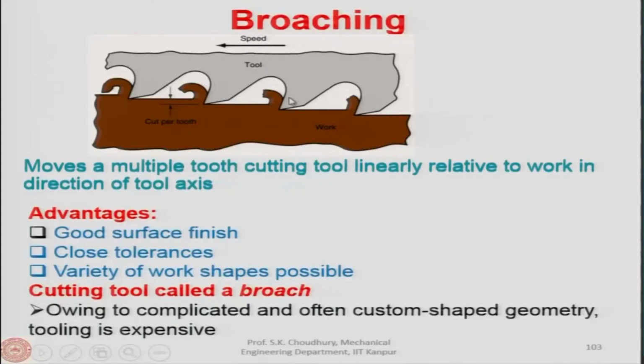This is the advantage of broaching, that here you get the machining process done by one tool, and the feed motion does not have to be provided.